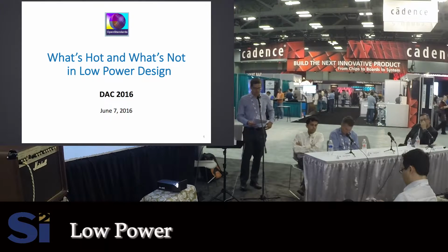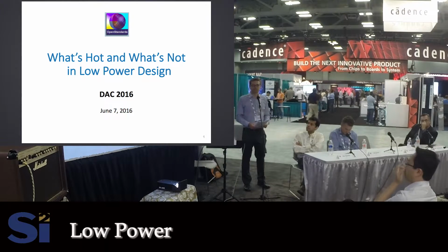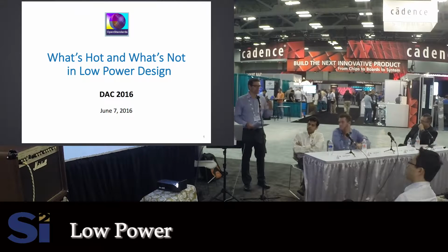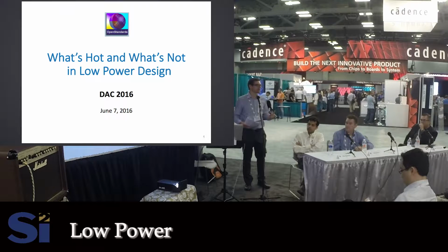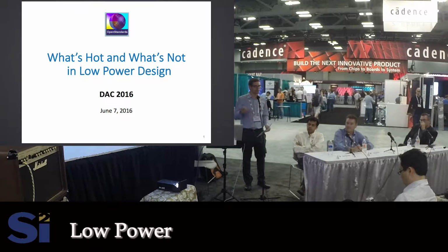Before I was into low power, I started my career in silicon implementation, and Jerry showed a little bit of that earlier. Back then, in silicon implementation, synthesis, EDA, the challenge for a block was how do you close the timing? You'd spend a lot of time changing RTL, over-constraining, and using tooling knobs in the synthesis tool.